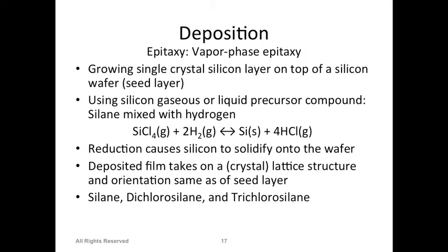You can grow carbon, by the way. If you can grow carbon, you can make a sheet of graphene, right? Or you can use this similar process to grow maybe carbon nanotube, which is again carbon in certain orientation, right? If you control the process conditions, that's how they actually use CVD to grow carbon nanotubes on the surface.